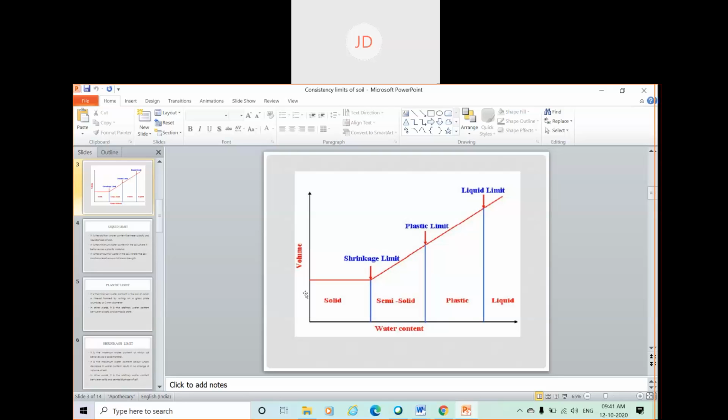Suppose you can also imagine a three-phase diagram of soil. Say, a two-phase diagram of soil. Suppose for a dry soil, it will be a two-phase diagram. That means below is soil solid, and above are voids which contain air, for the time when the soil is dry.